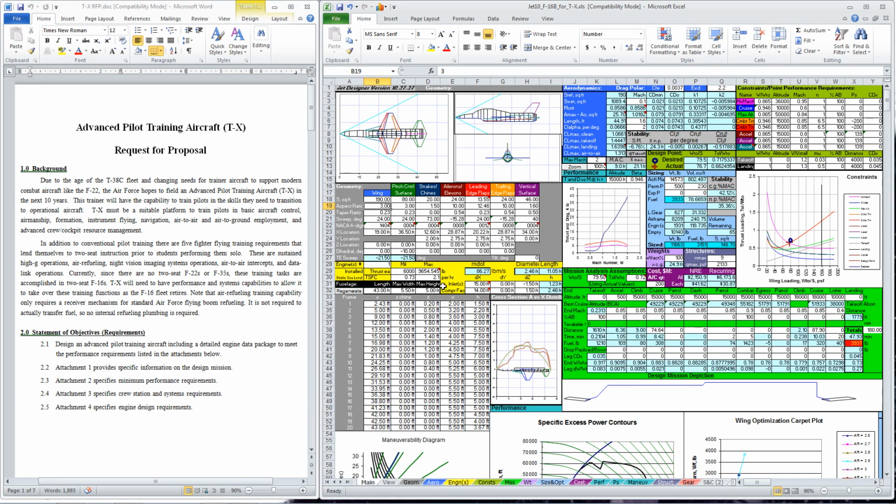Okay. And then let's increase the thrust just a little bit, 6,500, to give ourselves a little bit of a margin. We got to go to about 15,000 pounds. And very good. Notice that the sizing equation is now giving us the same result as our actual within just a couple hundred pounds. So it might be worth running optimization one more time, but I think we've got a really good wing plan for him. I think we've got a well optimized airplane.